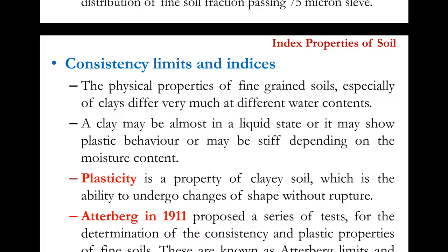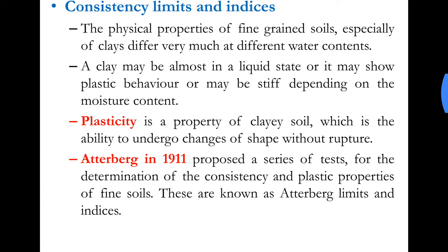If the soil sample has more water content, then it behaves like a liquid or a semi-liquid. As the water content reduces, it behaves plastically, like a plastic material, it deforms shape. Similarly, as the water content keeps on reducing, the soil behaves like a solid object, like a brittle object. So based on this water content, we establish a few limits. These are nothing but the consistency limits.